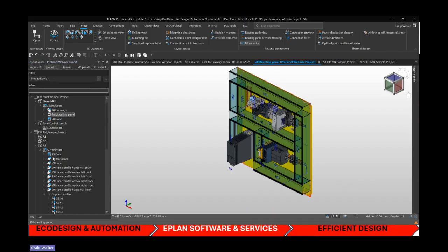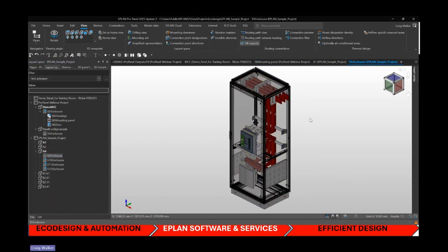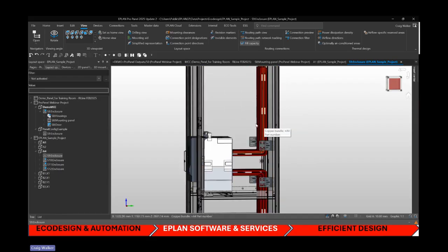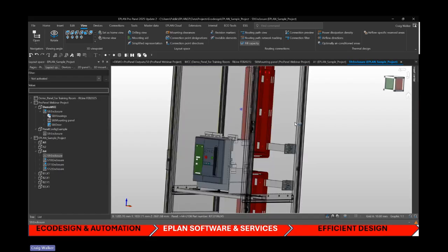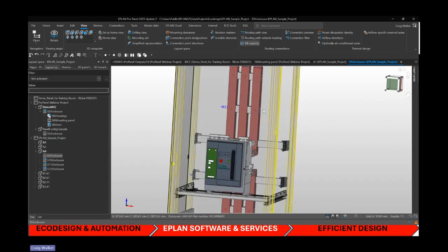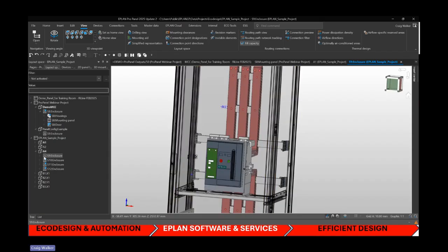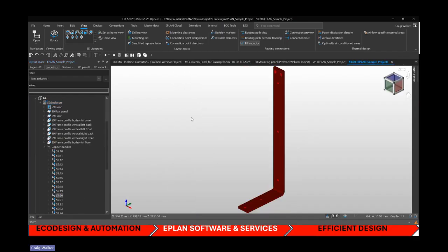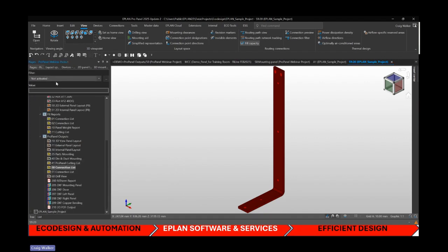That's my mounting panel on there. Bingo. So you can see here, it's got quite complex bends, separators, drilling patterns carry through as well from one through the whole set. And then you can export just individual single bus bars. It'll generate an output DXF file, which I have an example here in Paperspace.